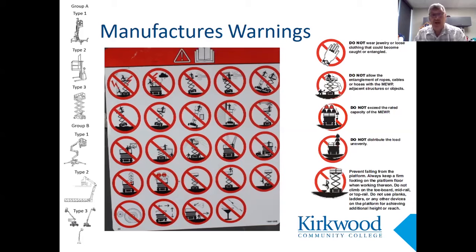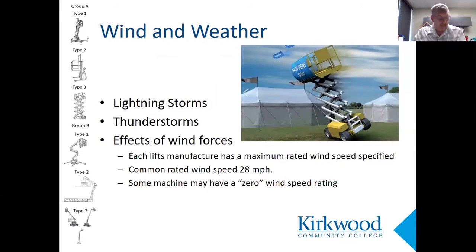So again, take your time and look at these manufacturer warnings. Wind and weather. Well, this really came to light in October of 2010 after a scissors lift blew over at the University of Notre Dame practice, which took the life of a student that was filming the practice. After a six-month investigation, the main reasons for the tip over were released, and one of them was a sudden, extraordinary 53-mile-an-hour burst of wind.